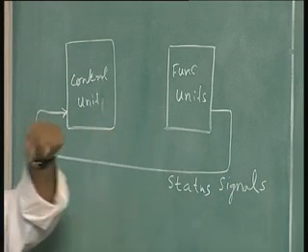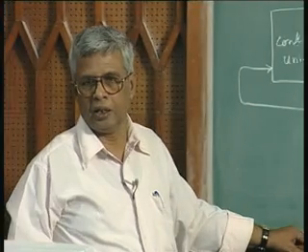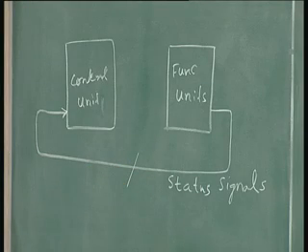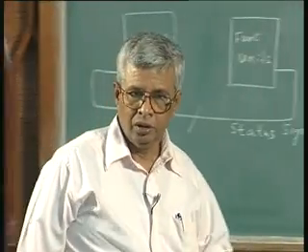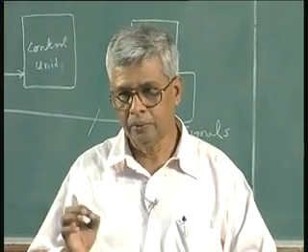The one line does not mean only one signal. In digital parlance, in digital convention, they put a slash. When you put a slash across the line, it means there are many signals. Or they put a thick arrow. You might have seen this in books. A thick arrow will mean several signals, or a signal, the slash. If you know the number, you put the number here. If you do not know, you just leave it. So, several status signals are required by the controller in order to decide the next thing to do, right.